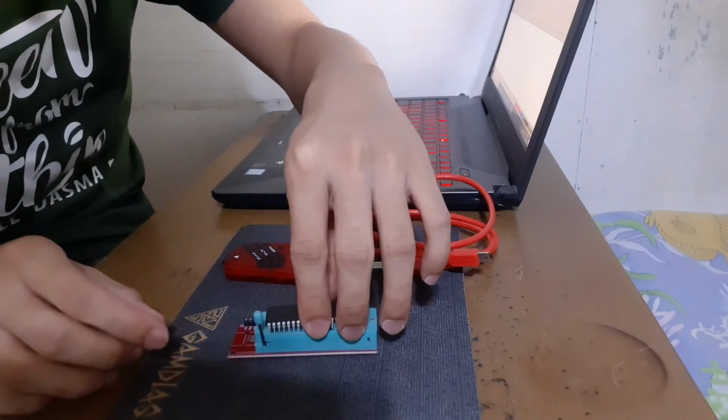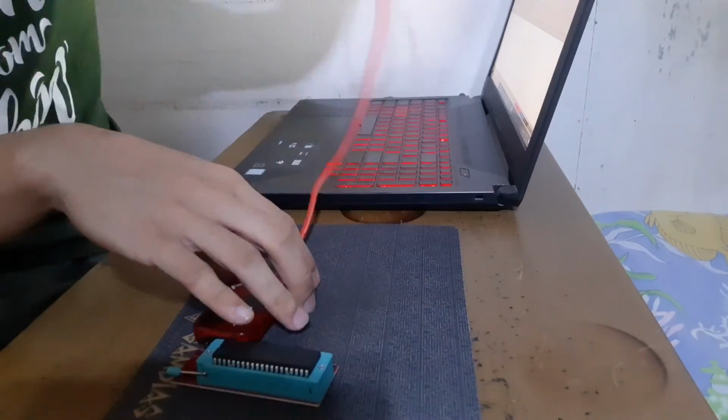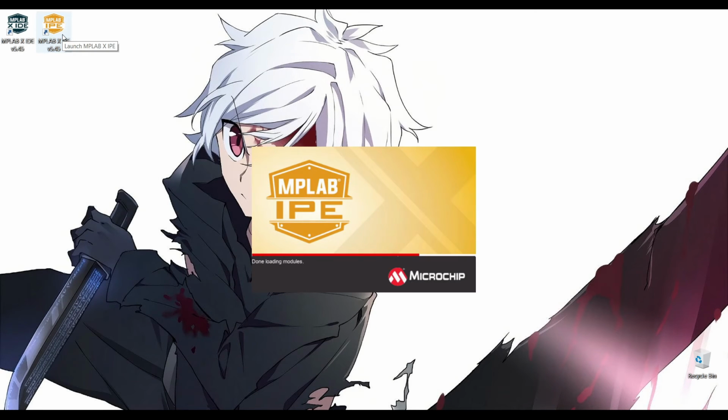Now we will connect the PICkit 3 and ICD 2 with the IC to our personal computer to install the program. Now open the MPLAB X IPE to install the program.